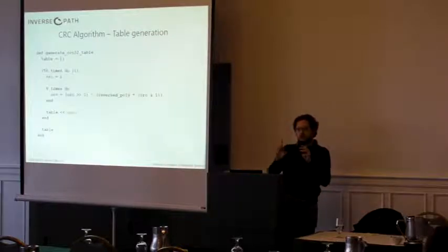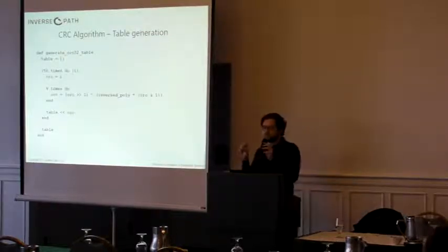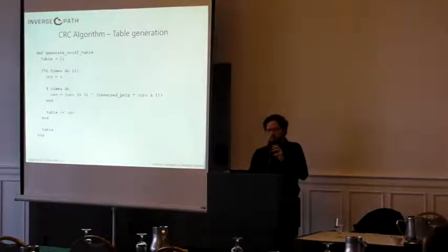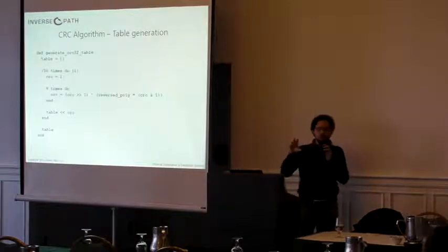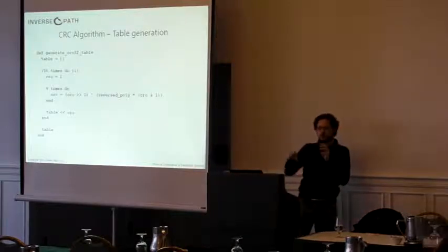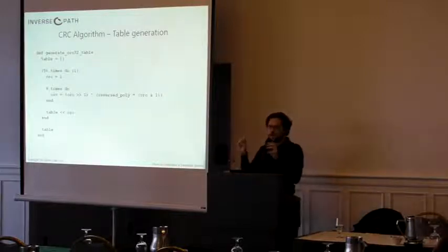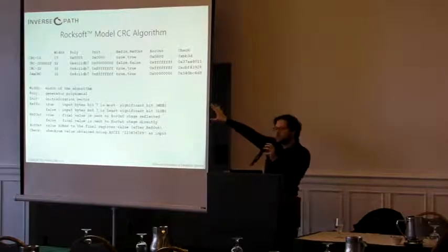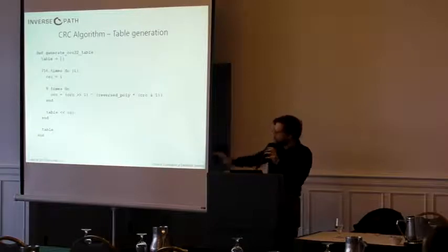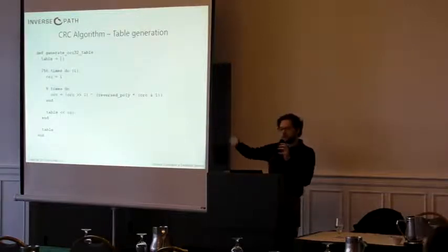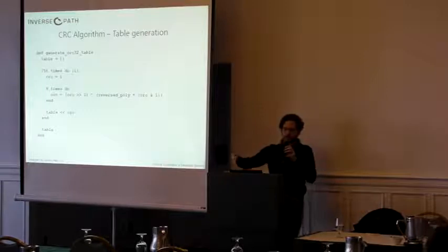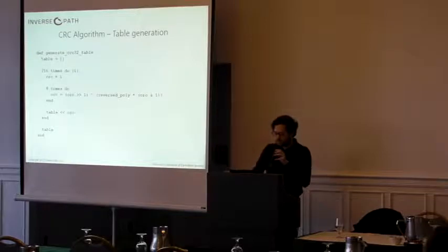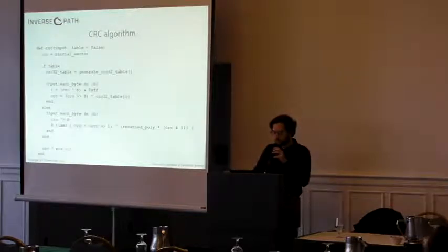And also you can easily find, if you have the firmware image, the assembly representation of the CRC algorithms like this one. You can either have an algorithm which uses a table, so a pre-computed table of values, or not, and also identifying the table, each of these algorithms will have their own table that you can easily compute with this code. If you search for the table within the code, that will give you a precise indication that the algorithm is being used. And I just left these for reference here in the slides. We're not going to comment on them too much at this stage.